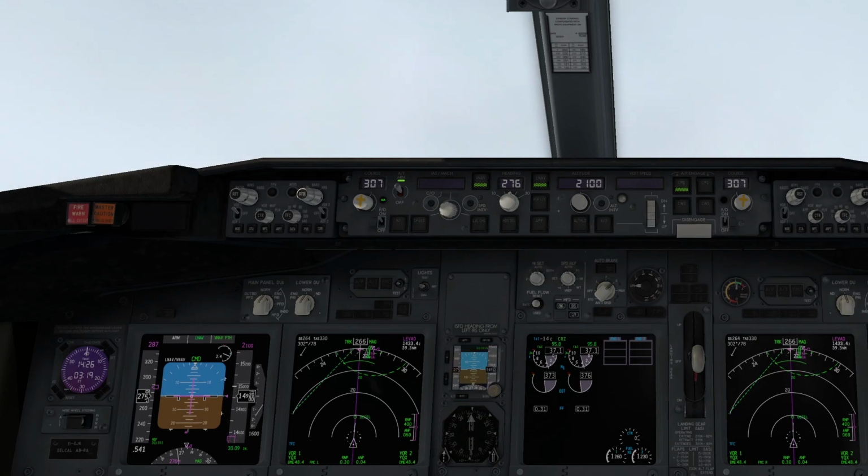It will probably reduce the descent rate a lot, and then resume when it is below 250, and at that time it will probably complain that drag is required, which is a little bit stupid. Now we have back thrust at 75% and down to idle thrust again.